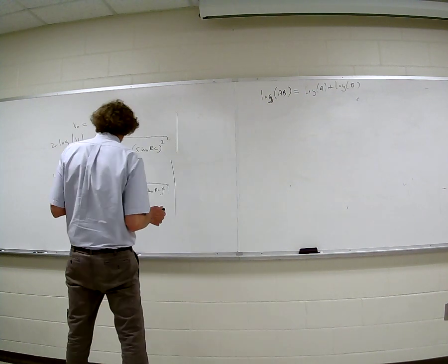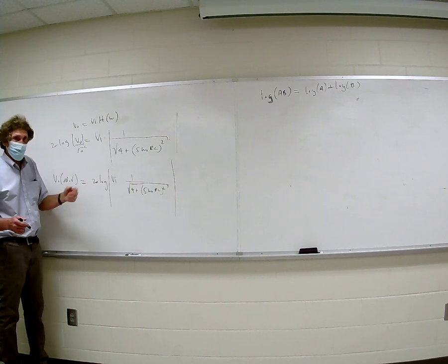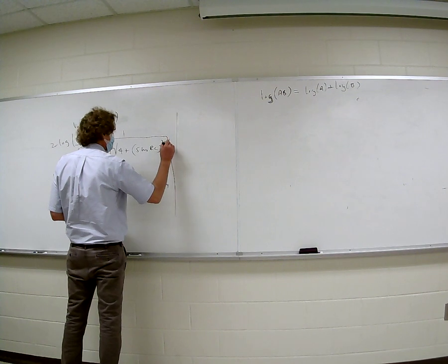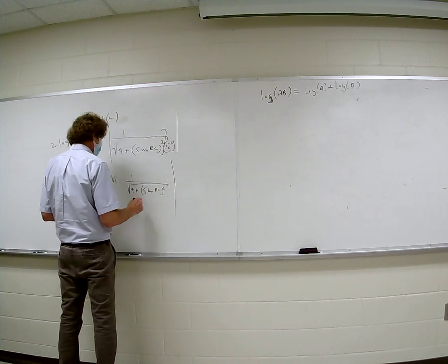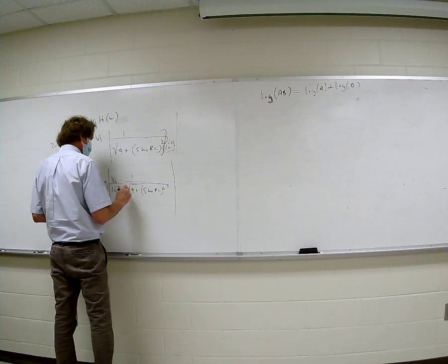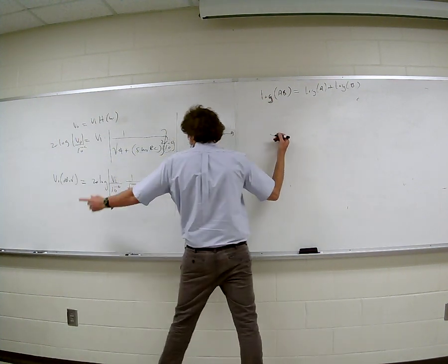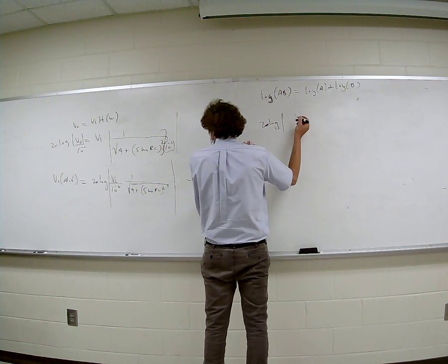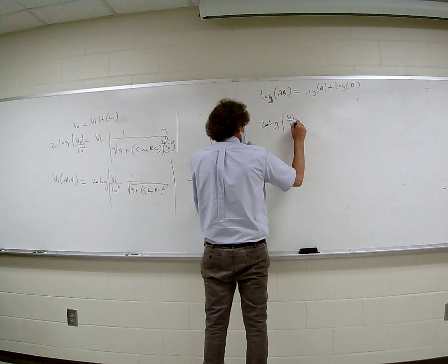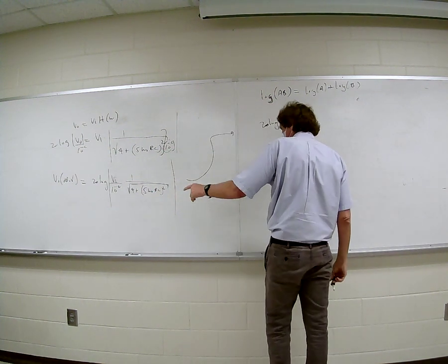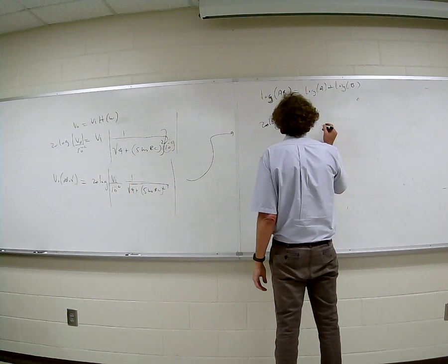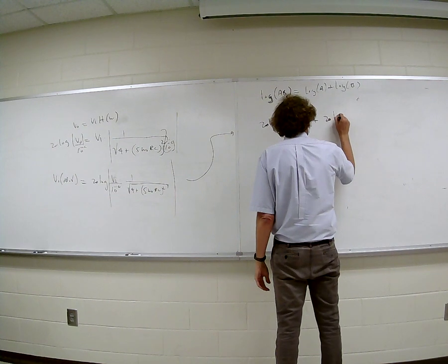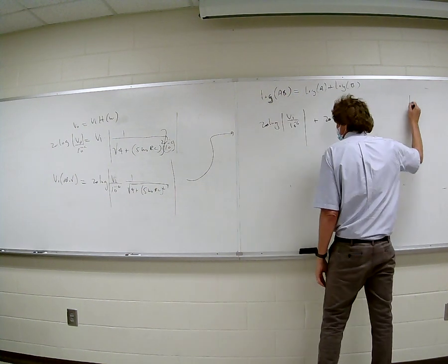Now, next, I'm coming to here. Well, you see I have the log of Vn, but I didn't put this thing divided by 10 to the minus 6 here, so it should be times 10 to the minus 6 down here, right? Times the whole thing. And there should be divided by 10 to the minus 6 here. When I expand that, I get 20 times the log of the magnitude of Vn over 10 to the minus 6. This would be at the fifth harmonic, right? Then it's going to be plus 20 times the log of the magnitude of that transfer function.